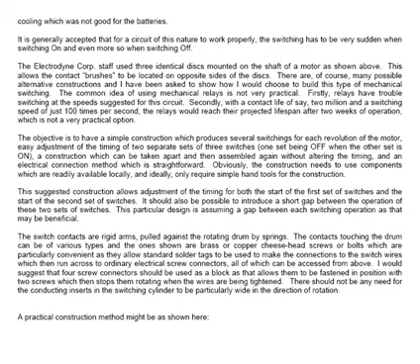I would suggest that 4 screw connectors should be used as a block, as that allows them to be fastened in position with 2 screws, which then stops them rotating when the wires are being tightened. There should not be any need for the conducting inserts in the switching cylinder to be particularly wide in the direction of rotation. So a practical construction method could be as is shown here.